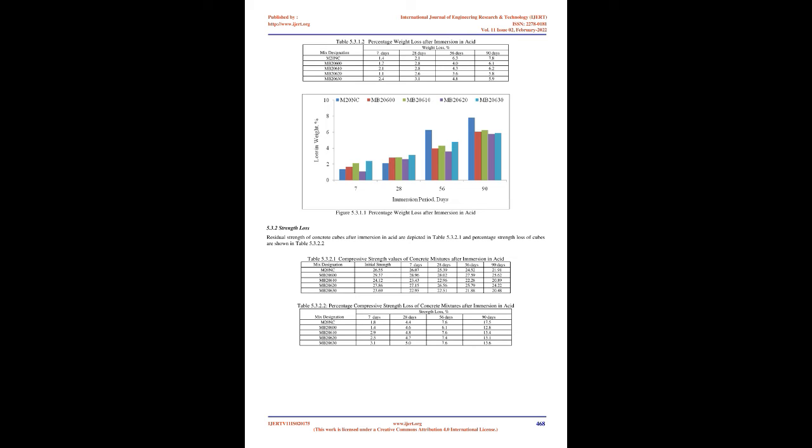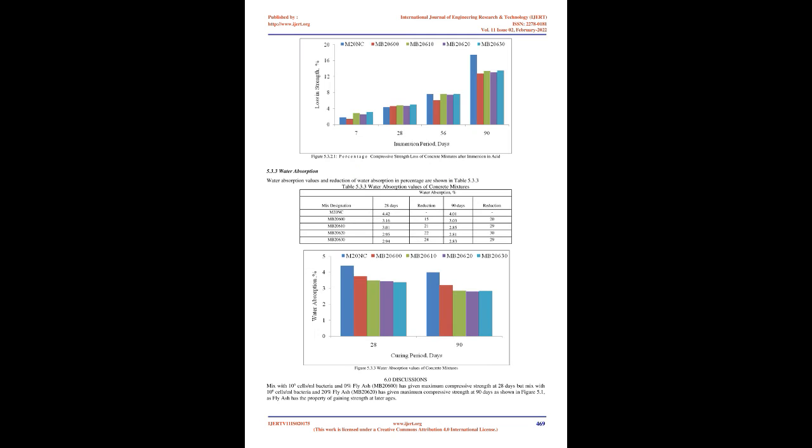4.4 Durability, Acid Test. The chemical resistance of the concretes was studied through chemical attack by immersing 150 x 150 mm concrete cubes in an acid solution. After 28 days of curing, the specimens were immersed in 5% H2SO4 and readings for weight and compressive strengths were recorded for all concrete mixtures at 7, 28, 56, and 90 days. 4.5 Water Absorption. Water absorption test was carried out on 100 mm³ specimens as per ASTM C642-97.